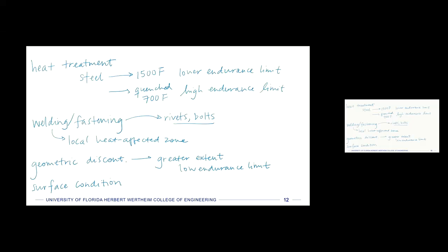That is a good idea, except some of those surface treatments create then a surface where there's different material properties and maybe a discontinuity in material properties near that coating, which can be an opportunity for fatigue crack nucleation. So there are some surface conditions that have a large effect.